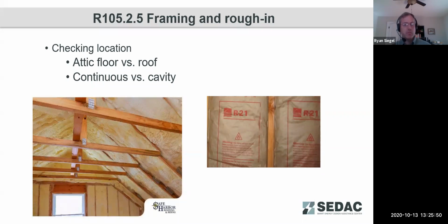This could dramatically change energy consumption of the building, where if the attic was not designed to be conditioned at all, and the insulation was designed to be on the floor of the attic, and it was later moved to the roof, and so the attic becomes conditioned or potentially conditionable space in the future, that could have an impact.